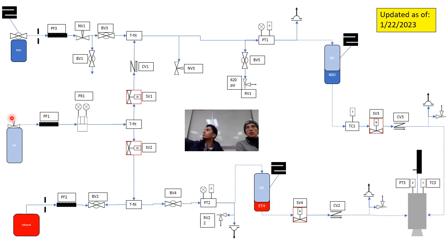What we can check though is to make sure our pressure transducers are reading 620 as expected, that our pressure gauges and pressure transducers match, that our thermocouples are reading expected values. If they're not, either the thermocouple is failing, or more importantly, and the conservative estimate is that there might be something wrong and the temperature is rising, for example, and we need to abort the test and allow it to vent.